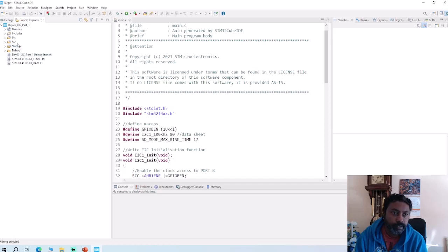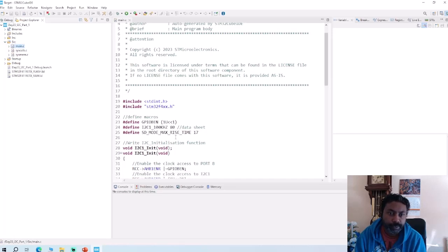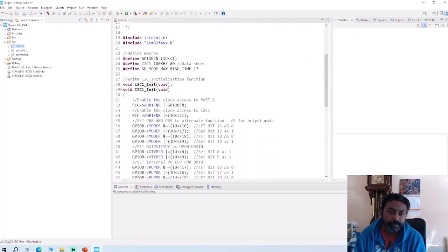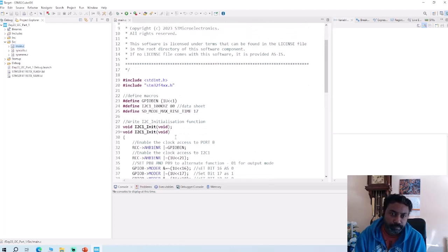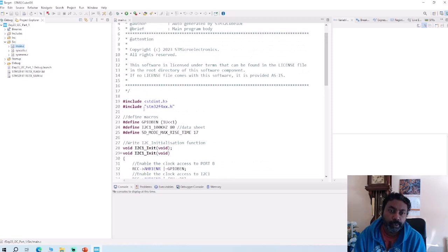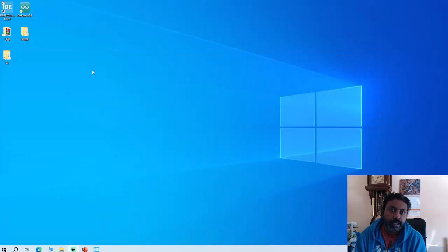So starting with the SRC, the source, you need to open the source and go to main.c. So that's our main.c program. Initially, as you remember, it comes with a few lines, so I need to delete that. And today we are also going to use the STM32F4xx.h, the built-in internal header files. As you remember on the LCD session, we did that path configuration and the symbol declaration.